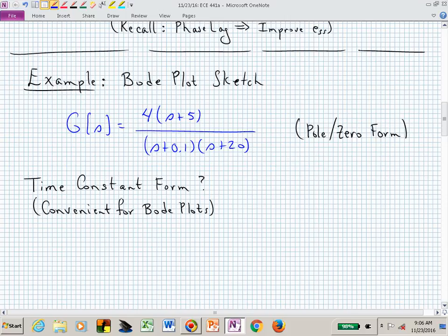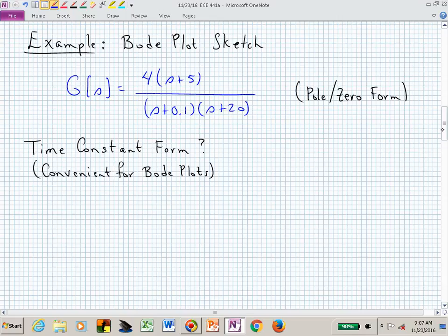You add a 1 to it? You add a time to it. Okay, well, how do we get the time of this? We factor that pole out and normalize that constant to 1 in each of these factors. And these are linear factors, and so it makes it even easier. Meaning, in this particular case, we can't change the transfer function unless we're introducing a controller.